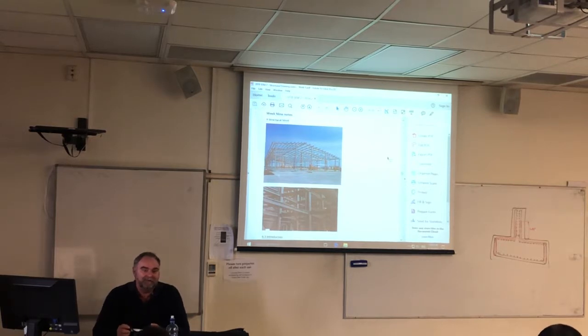If you copied someone from last year that said, hey bro, this is easy to do, you just do this, it's quite possible you were wrong, because last year there was more fill than there was cut. If there's more cut, what you do is you apply the 1 point times the cut by 1.3 and times the fill by 1.25. Then you get a new balance at the end. It works out as roughly 5%, but it's a little bit different to 5%.